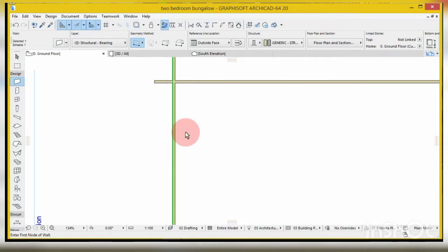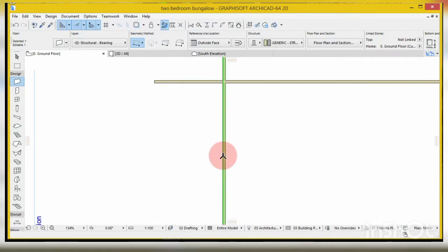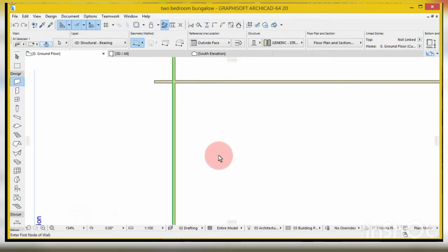So I will see a plus sign on my cursor. It simply means duplicate. If it didn't appear, it means it's just going to drag. For example, if I say Ctrl D, it's just dragging this, and it has left that side. But that's not what I need. I want to duplicate it. So I say Ctrl Shift D. I will type the distance.